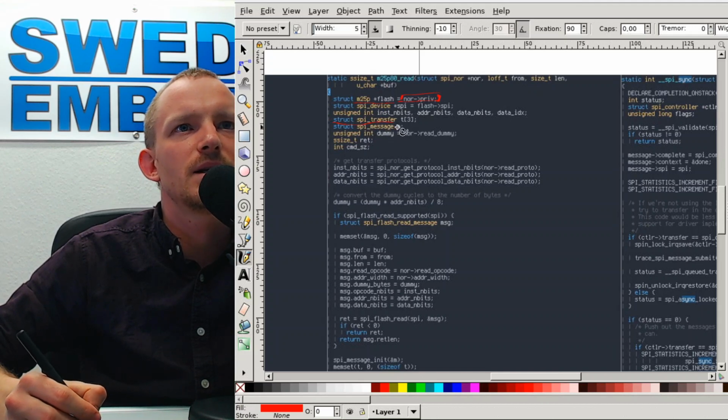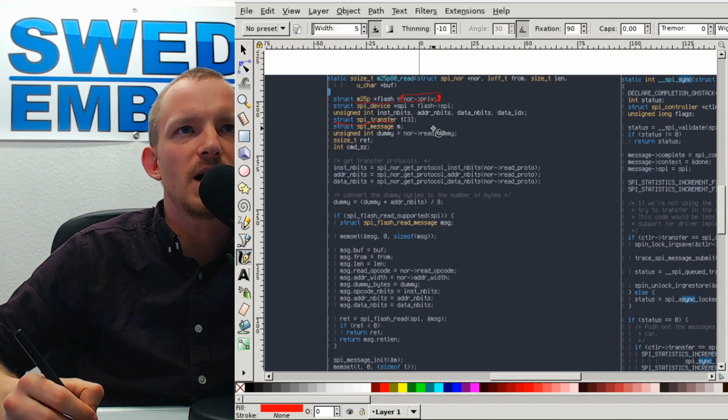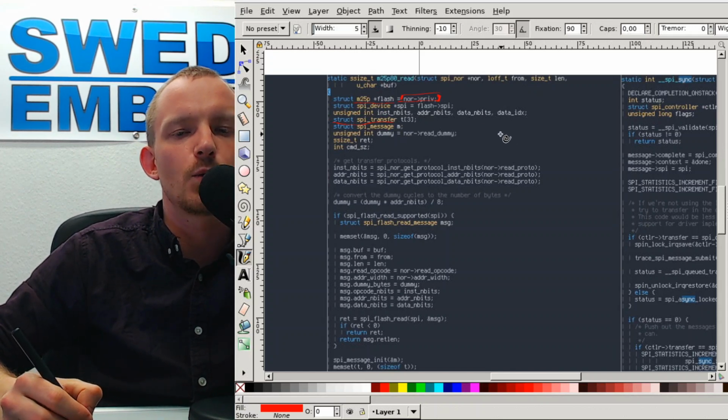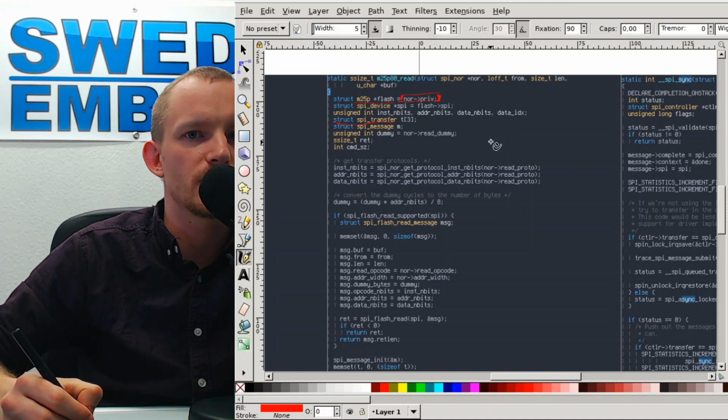It's much easier than if the API was just taking a buffer and just writing to the SPI port. Because think about it, the SPI port is actually writing first and then it's reading. So it's always this dual operation, even though you're still reading when you're writing.